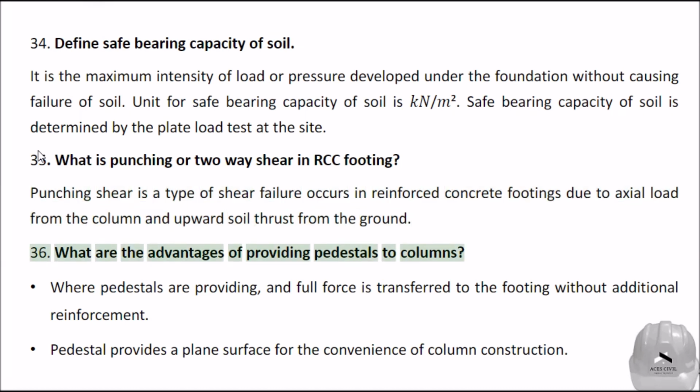What are the advantages of providing pedestals to columns? Where pedestals are provided, the full force is transferred to the footing without additional reinforcement. A pedestal provides a plane surface for the convenience of column construction.